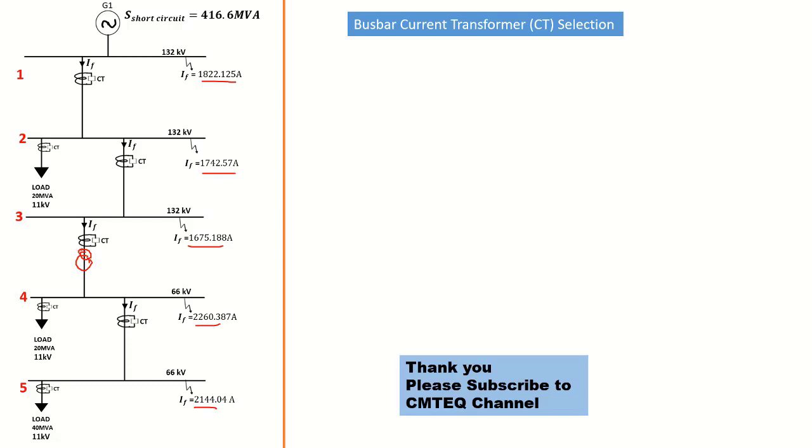There is a transformer there that is changing from 132 kilovolt to 66. So now we can see the voltage go down and the current go up. The current goes up as the voltage goes down to maintain transformer power transfer properties. Okay, so in the next tutorial, that is what we will be doing: how to select these current transformers here.